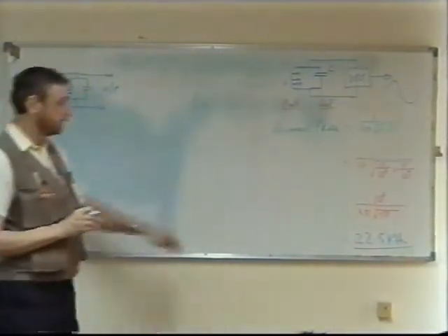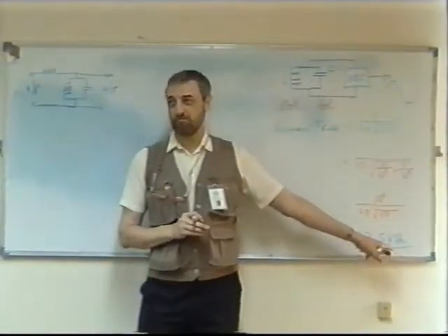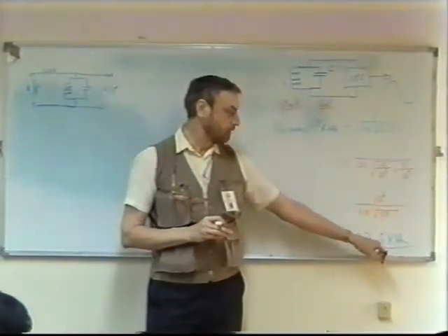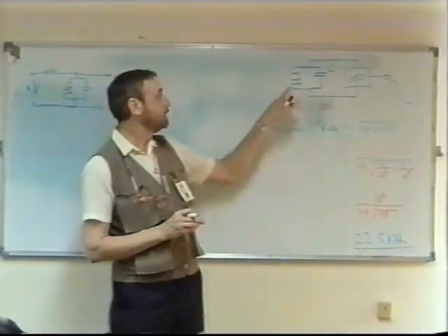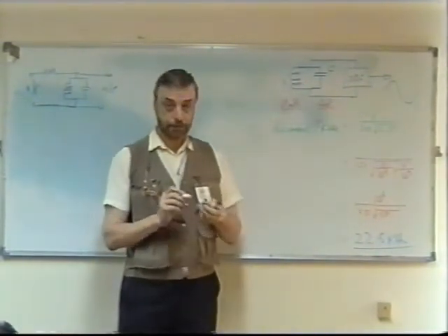Yes, this here is 22.5 kilohertz, isn't it? Which is really like the higher audio, just above the audio band. So really that's too low for us. If I really wanted to make a practical radio frequency circuit, I would need to use much smaller values of L and C. We'll do some examples of this in a minute.